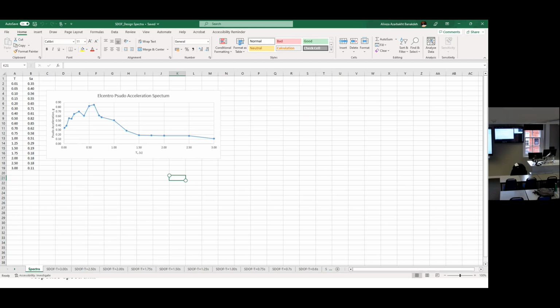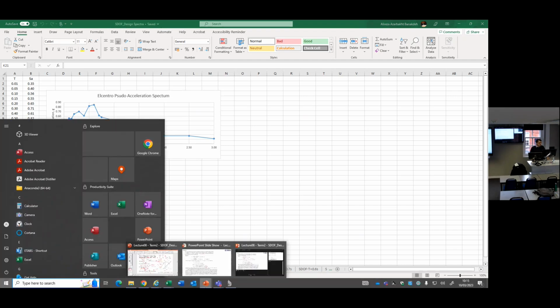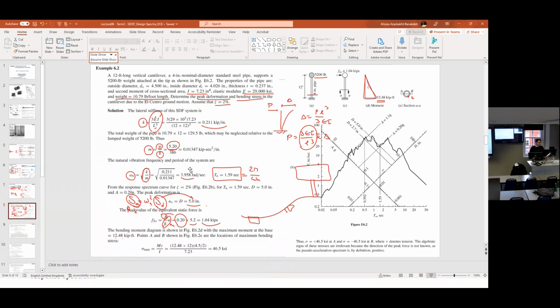The induced force in your structure depends on the mass and the stiffness. As a designer, you don't usually have much flexibility to play with your mass, because mass is mass. You need some walls, some floors. So mass is relatively constant and out of your hands. But the stiffness is in your hands. And when you play with this stiffness, you're playing with the external forces coming into your structure. That's why increasing the section property doesn't solve the problem in one go. You need to go for a third case as well.